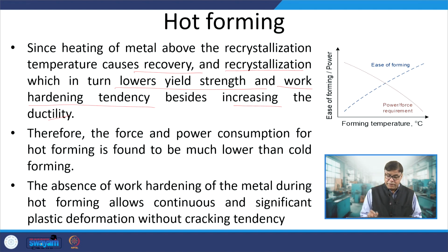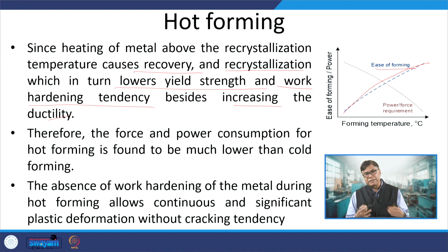Because of this reduction in yield strength, reduction in work hardening tendency, and increase in ductility, the ease of the forming process is enhanced with increasing temperature. And since the material has got soft and ductility is enhanced, it requires lesser stress, lesser force to facilitate the plastic deformation, and that in turn reduces the force or the power required for hot forming.